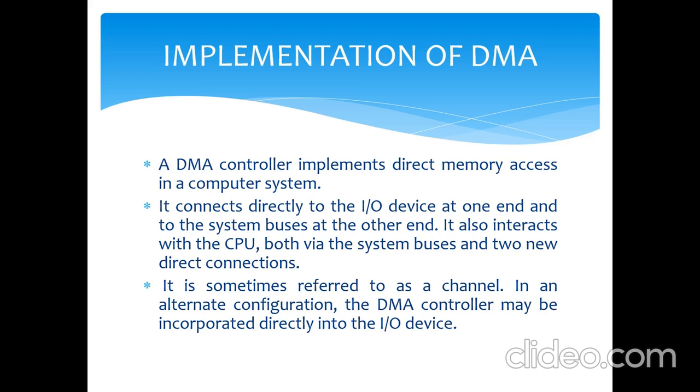It connects directly to the IO devices at one end and to the system bus at the other end. It also interacts with the CPU, through both the system bus and two new direct connections. It is sometimes referred to as a channel. In an alternative configuration, the DMA controller may be incorporated directly into the IO device.